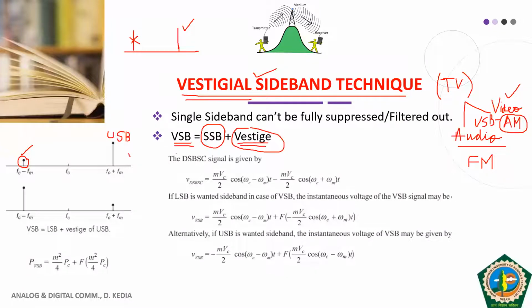Now this above figure was with respect to the upper sideband. If you keep the complete lower sideband, then you will keep a part of the upper sideband. And these two parts are called vestige. So in case of vestigial sideband, we have one, say, lower sideband, and another is the vestige.